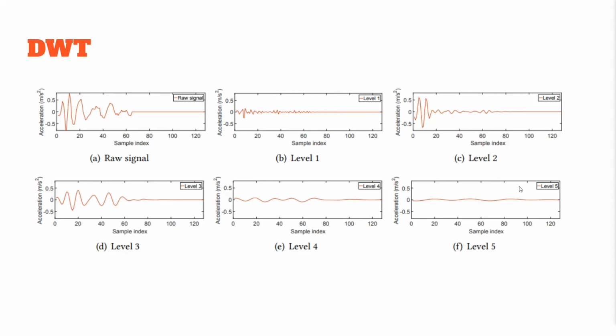To reduce noise in the SCG signal, we only use detail coefficients from the second level to the fourth level as the feature vector for the heartbeat's authentication.